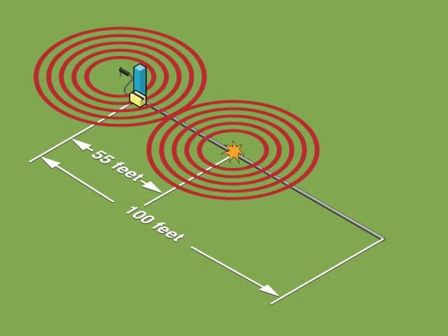You have a section of cable that is 100 feet long. There is a break in the insulation of this cable, causing an earth return fault at 55 feet. It is very likely that the areas of detection, or pools, will overlap on this short section of cable. You would never know that you have passed from one area of detection to the other.